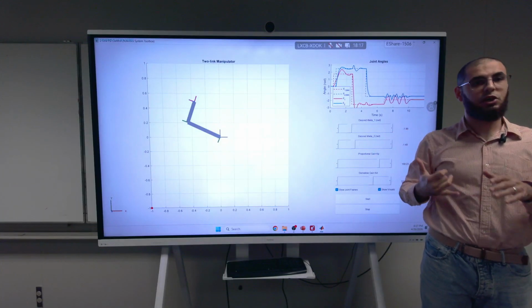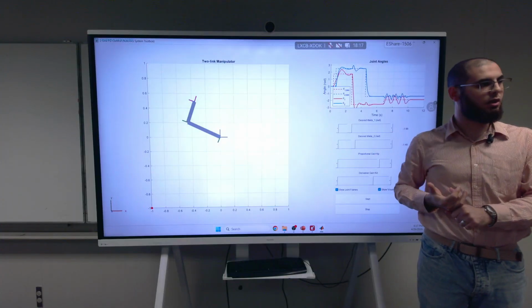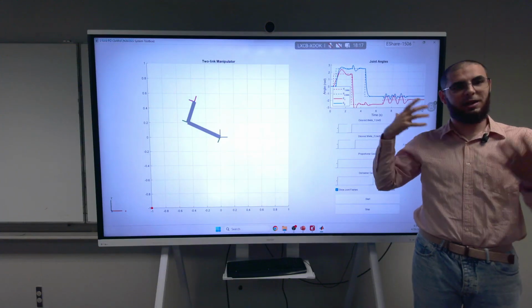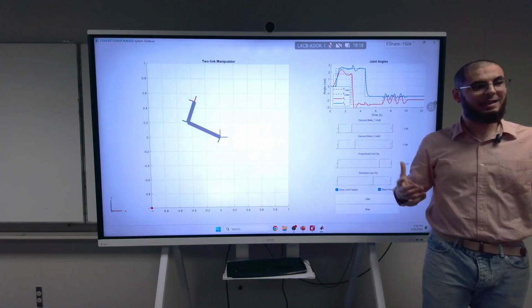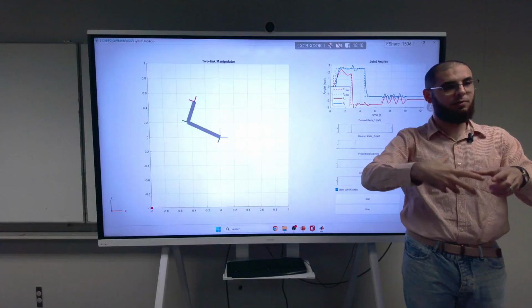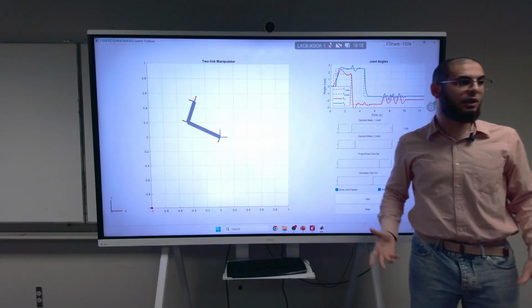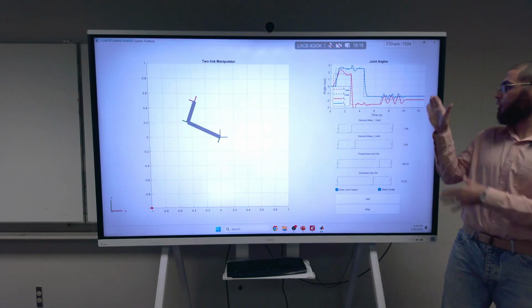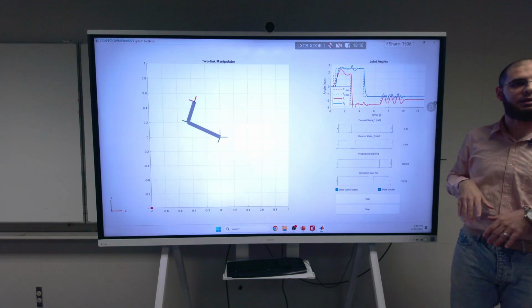You can start to do interaction with it. Next lecture, inshallah, you can even do teleoperation with it, with haptics and stuff like this. If you just imagine that you have springs and dampers, you can even combine springs and dampers. You can do collaborative manipulation in this way and so on. So you can really go crazy, and it's all very simple. Just PD control. And you see here we increased the damping and things became stable.